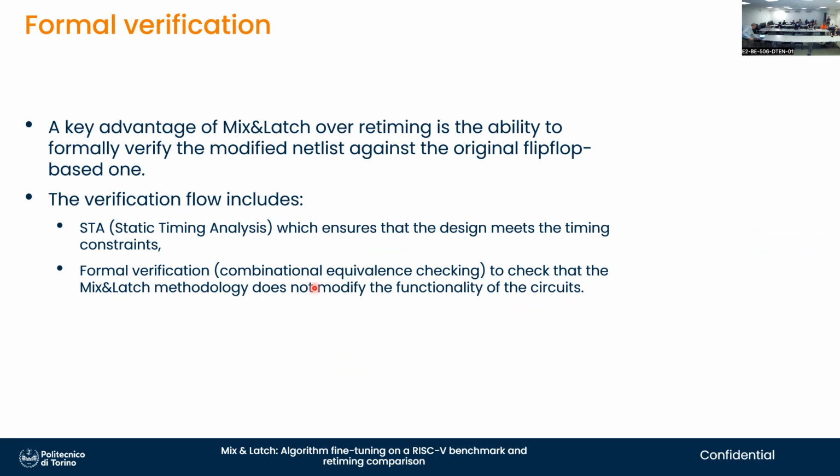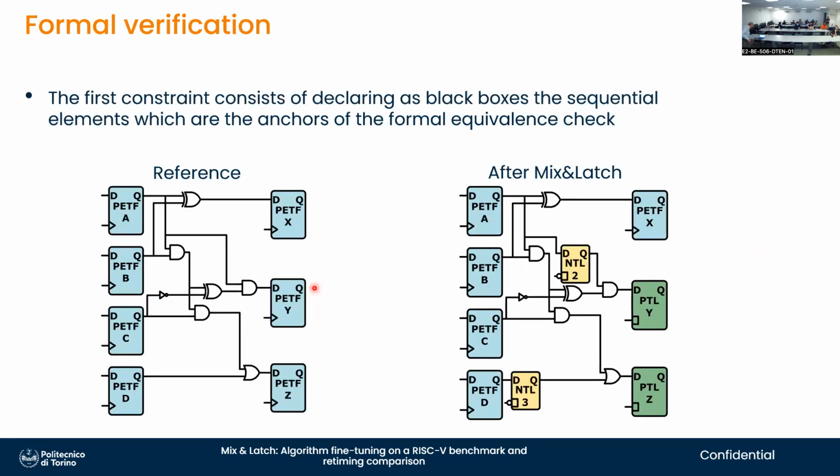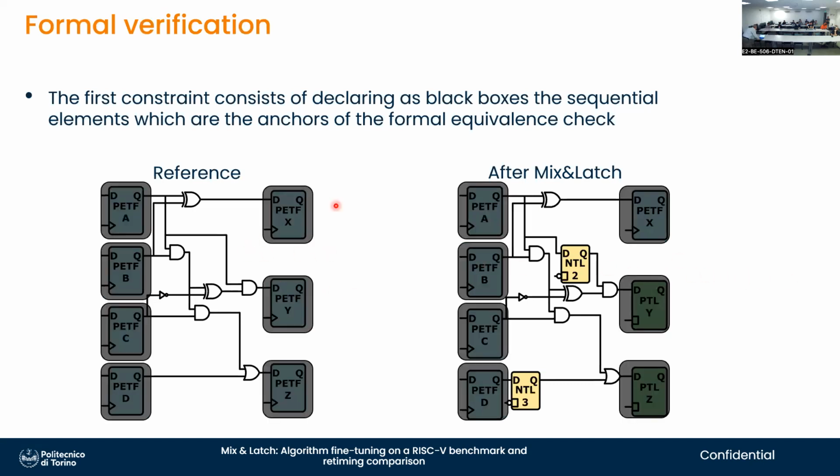And then we use equivalence checking by using a trick, namely, we take the original circuit, and we turn the registers that are the replacement of the original ones into black boxes and tell the equivalence checker, look, these are exactly the same. Please check the combinational logic in between. Check that I didn't leave any open circuit or any short circuit during layout. Check that I didn't convert an AND gate into an OR gate by mistake during logic synthesis.